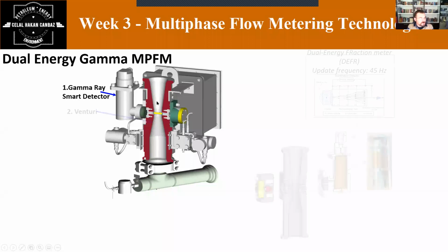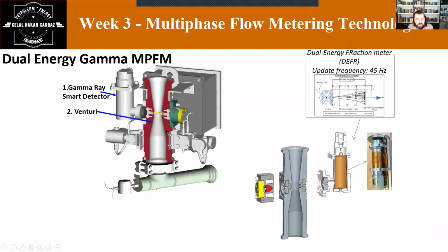As I mentioned, there is a venturi section. This is a venturi spool. It is used to cause a kind of line size restriction between the vertical section of the inlet tool and the throat. The line size restriction is important to calculate the pressure differential as well. It is a kind of conventional venturi, used in the vertical direction.